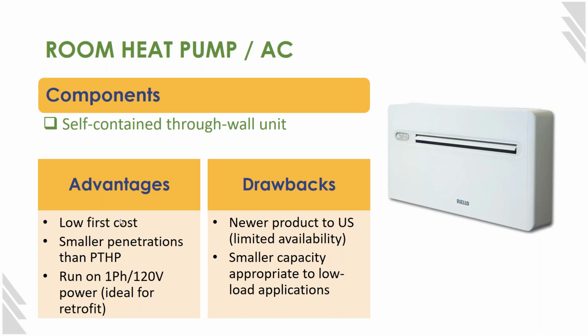So advantages of these systems, they're also quite low first cost. They have smaller penetrations than a package terminal heat pump, and this is a huge advantage. They run on single phase 120 volt power. So depending on your local building codes and requirements, they can be directly plugged into a wall outlet, which could be really ideal for retrofits.